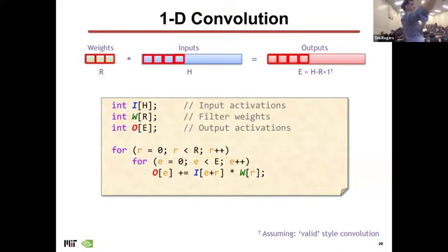Well, I mean, this is kind of simplistic, right? Because it sort of assumes, okay, so if I have one convolution that I'm putting into an array, you'd have W0 be one element. So in this example, you would have R different PEs, okay? And then each PE would be responsible for one inner loop, and then it would pass its output to the next inner loop. And the way you keep them all active is just keep feeding the new activation. So they're each doing a different thing, right? After they finish their inner loop.